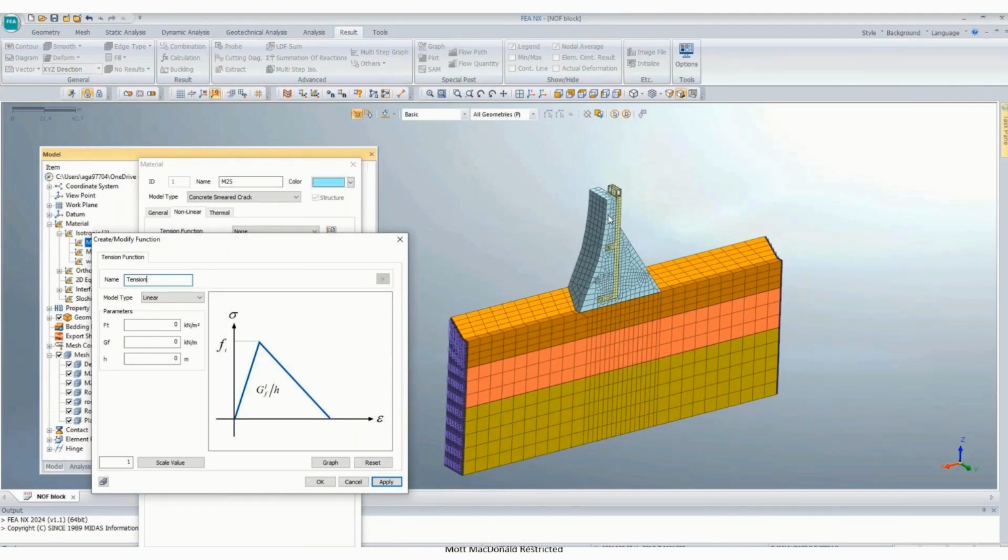And in manual computation, you will find the weight will balance all these stresses, and you will get a compression here for load condition B, considering that uplift, whatever is mentioned in the code at different levels. Actually, those criteria are not applicable for the numerical analysis, for finite element analysis.